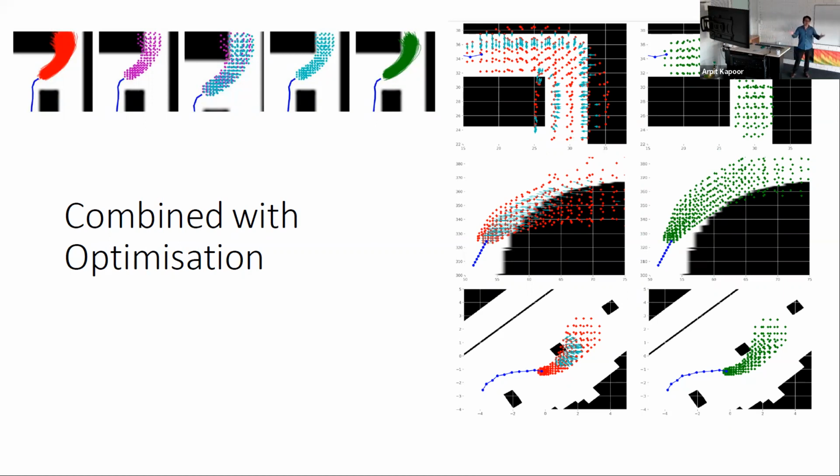occupancy. So I mentioned before, going back to the environment representation, that we can get these continuous representations, right? Now the benefit of them is you can actually get gradients with respect to the occupancy. So you can push these distributions of trajectories, or nudge them, into places that have lower occupancy, right? So lower chance of being in collision.